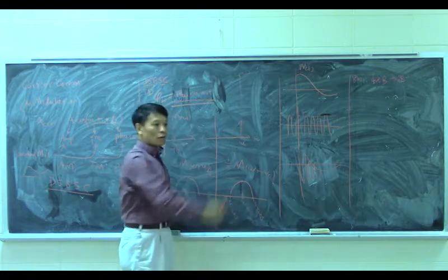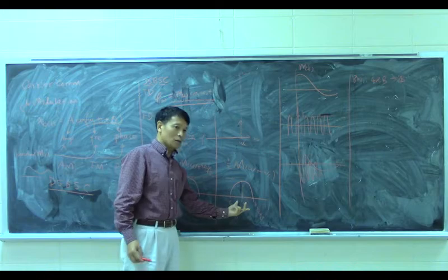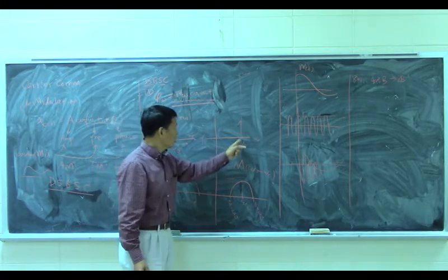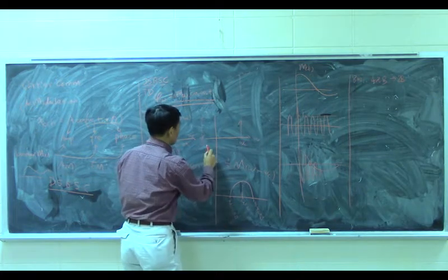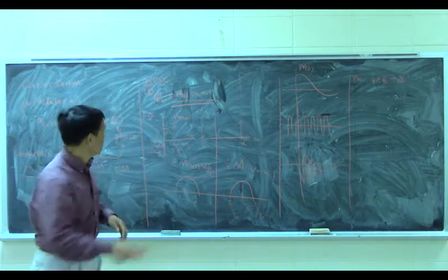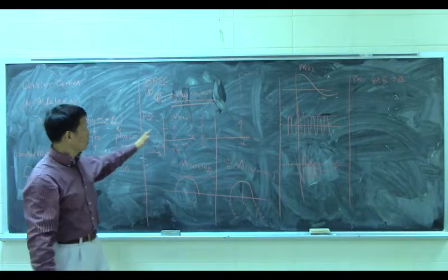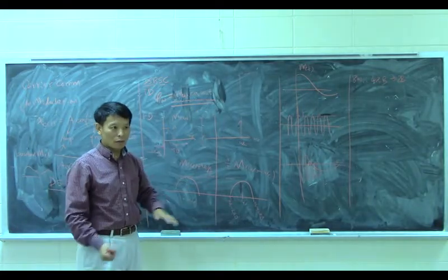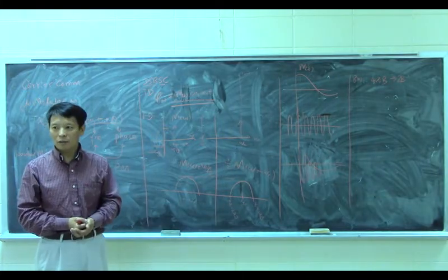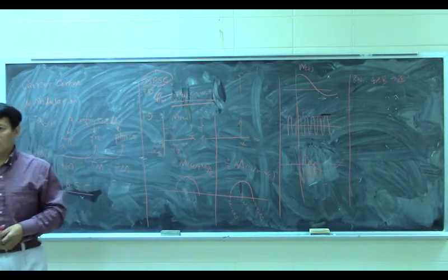We don't have this information. We only have this copy, just shifted to be centered at omega c or negative omega c. We don't have the impulse at omega c and negative omega c. That's why it's called suppressed carrier. The carrier signal is gone. We only have the baseband information, but at a higher frequency. So that's why we get this name: double sideband suppressed carrier.